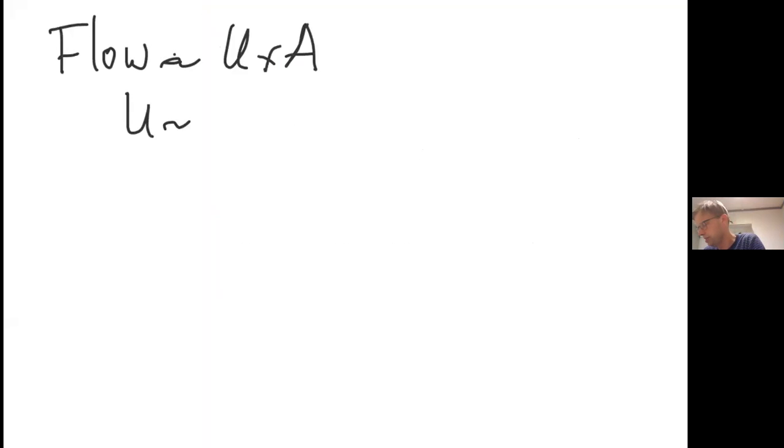So we have the flow. That is something like U times the area. U scales with the rotation speed times the diameter. The area scales with diameter squared.